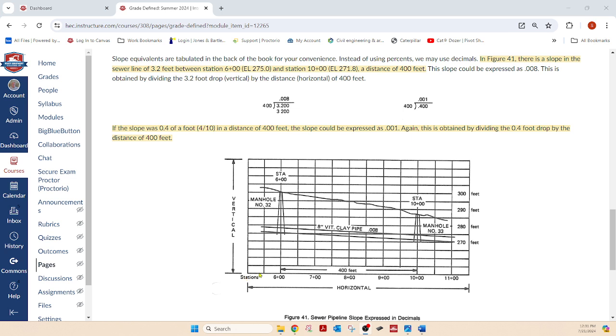This is your distance down or up station down the road, and this is the way surveyors do it. Like from somewhere back here to here is 600 feet, and you write that 6 plus 00.